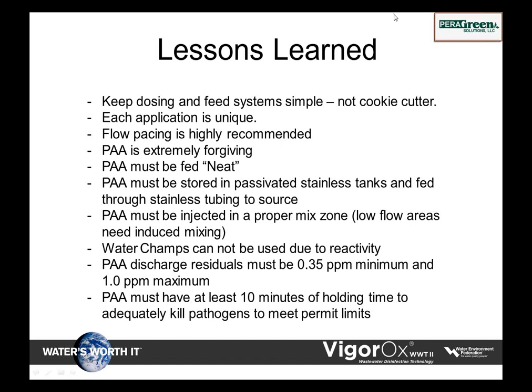One of the limits we found at Steubenville, though, is that the pumps they had were not variable speed. So at times we may have 8 million gallons a day, and then it drops down to 3 million. I was there one afternoon and we saw 0. So those are some of the problems we had to overcome hydraulically to demonstrate how the product worked.